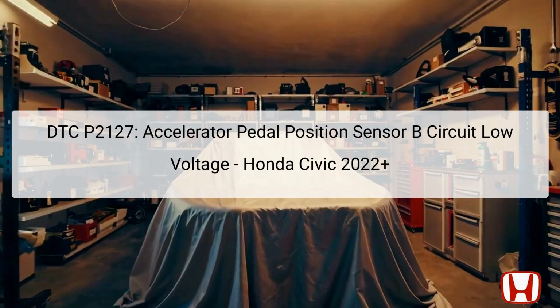When this voltage is low, the engine control module, ECM, or powertrain control module, PCM, might detect the issue, register a fault, and store the DTC P2127. The APP sensor is integrated with the accelerator pedal module, located near the driver's footwell, providing essential data to the PCM for proper engine operation. Proper troubleshooting procedures must be followed to ascertain the exact cause of the issue and rectify it efficiently.